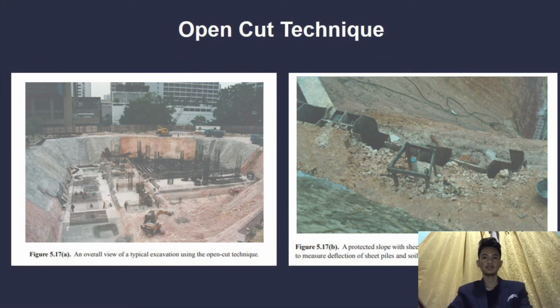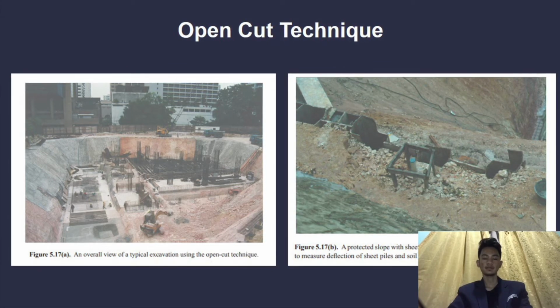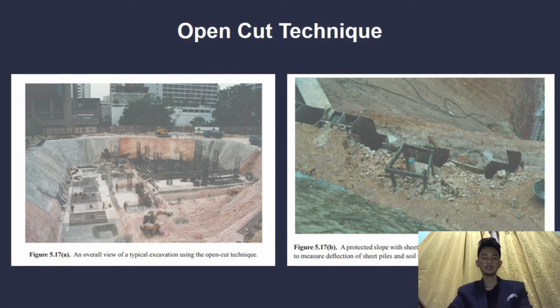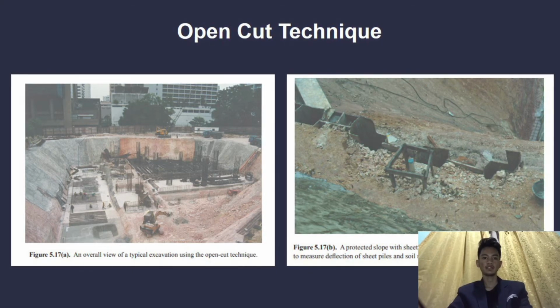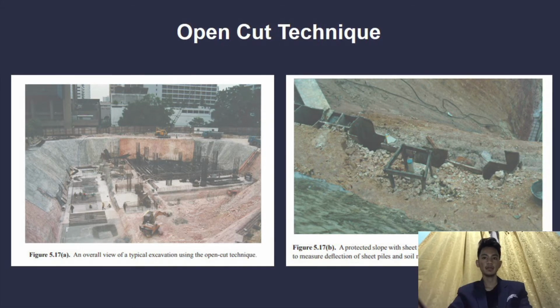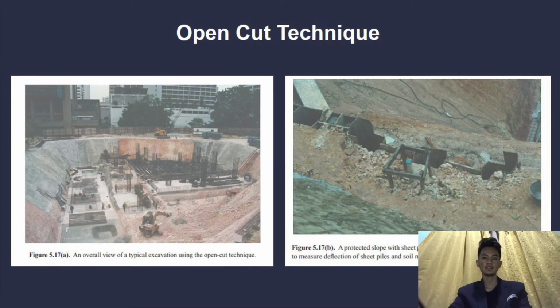Rods are inserted into the soil alongside the slope. Nets are cast over the slope and concrete is sprayed onto them to prevent the soil from eroding or sliding during rainy days. In some cases, pile seating may be provided to reduce differential settlement to the adjacent buildings.